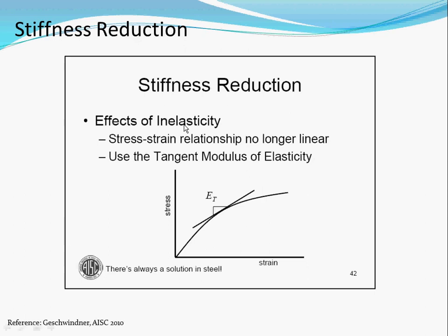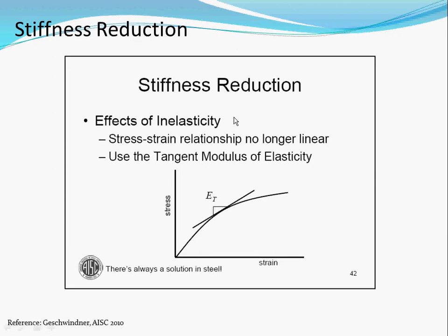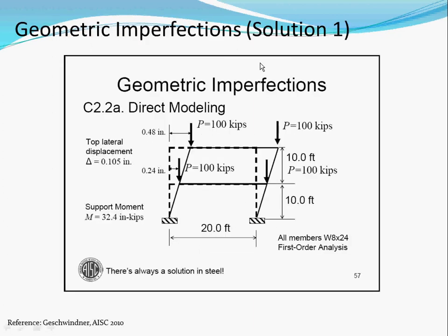Okay, stiffness reduction. That's related to the stress and strain. When you're doing an elastic design, this is elastic. So no big deal. But when you're going into the plastic range, that's K, or they use a tau, the E, but that K value is reducing from a high number to a smaller number when you go horizontal. So that's what they mean by stiffness reduction.